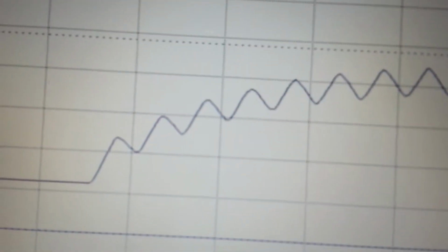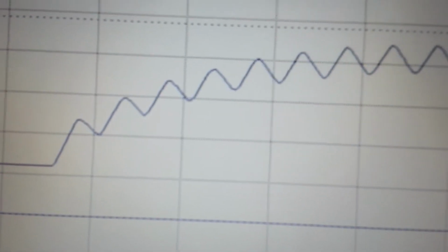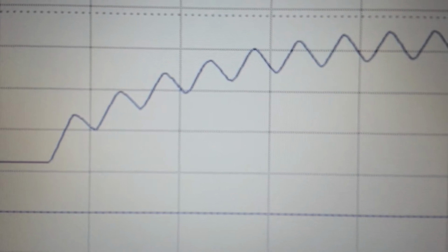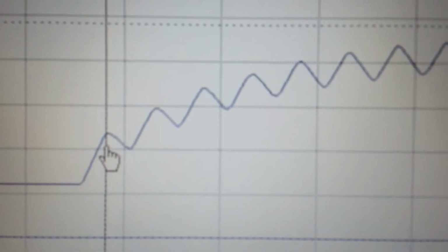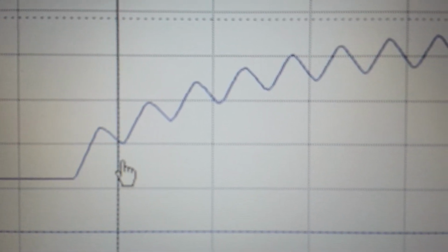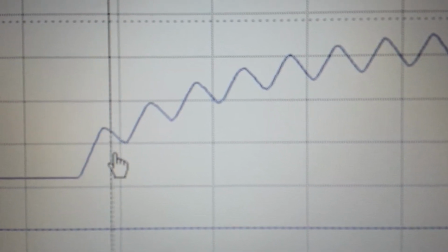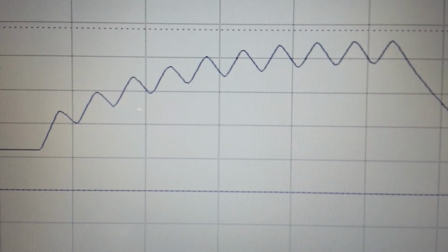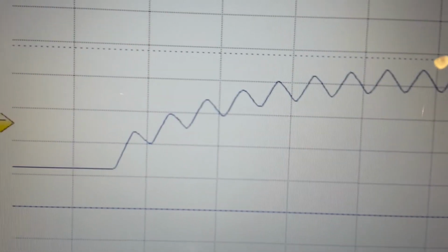So when you get your pulse frequency doubling, I hope I'm explaining this right so everyone understands, all you're doing is converting the 10 kilohertz 50% duty cycle to a 10 kilohertz at 100% duty cycle. When your inductor discharges, it's filling in that last 50% of the waveform rather than just having it drop off and discharge the capacitor. So it's allowing you to have step charging when you get the pulse doubling effect, as you can see here.